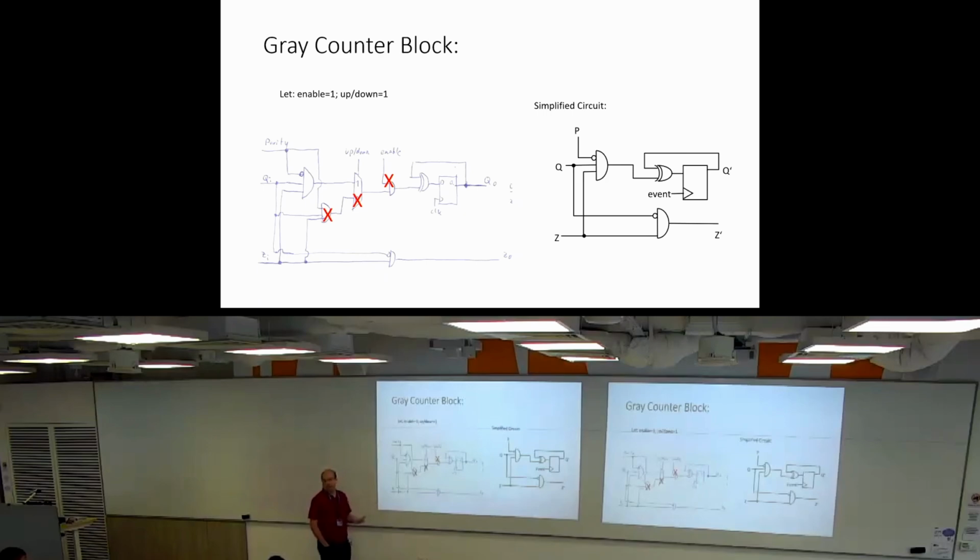Then you have a gray counter, which is relatively quick, but you require some read-only memory for that, or need to load the data for this memory page. So it has some drawbacks. In particular, you need to have these load and store operations on your memory.